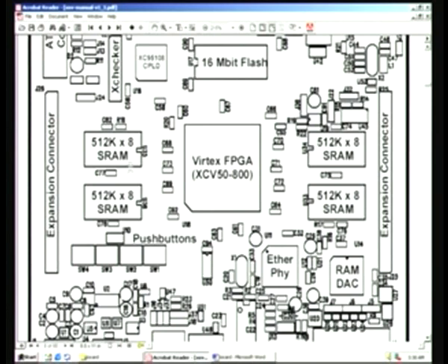or you do not want to use the internal storage. So you may have to put an extra card outside and connect that card to this expansion connectors here available on both sides, and while doing so you may have to disable this by appropriate jumper connection, which is available on the board, and all these details are available in the manual, part of which you are already having a look at right now.